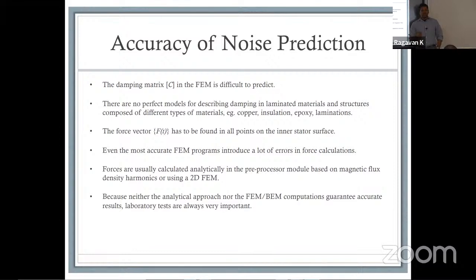If you remember, damping would be something like a spring motion, right? You're talking about something that slows down the motion. It's a material property, and we have a difficult time. We can only trust what FEA is doing, because unless you go experimental and calculate the real numbers, it can be difficult to predict that matrix C. And oftentimes you don't see very many perfect models, if any.